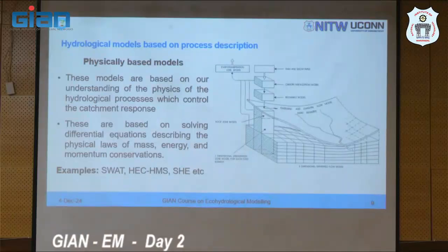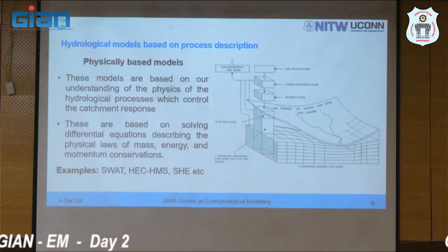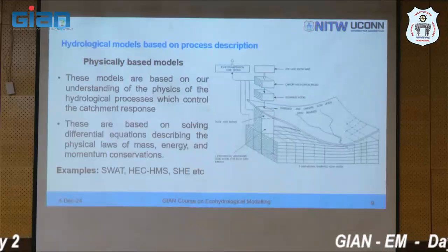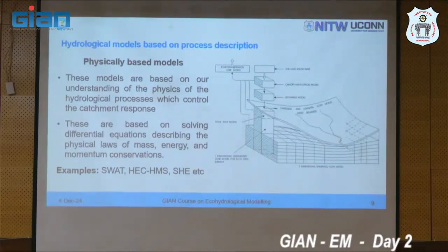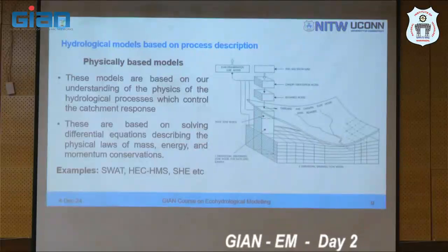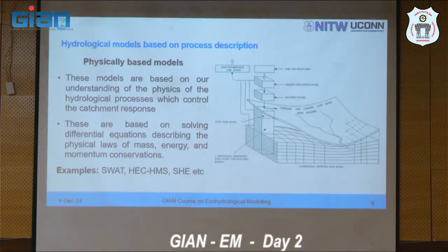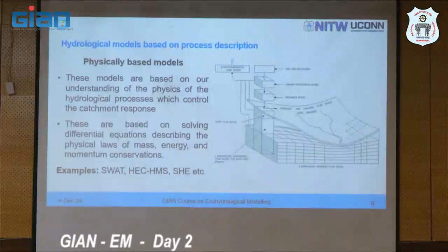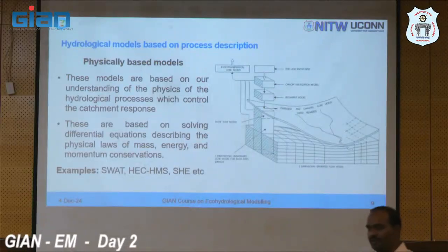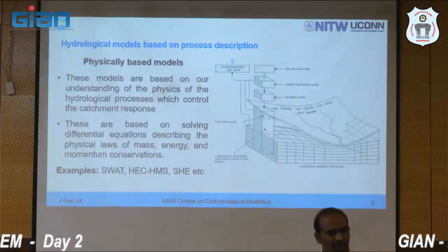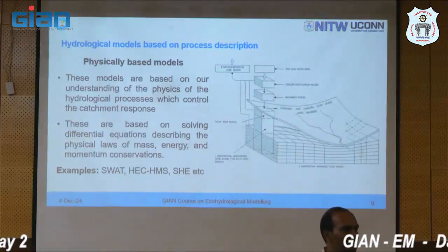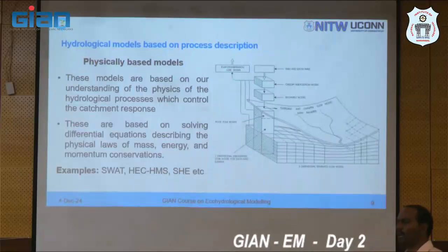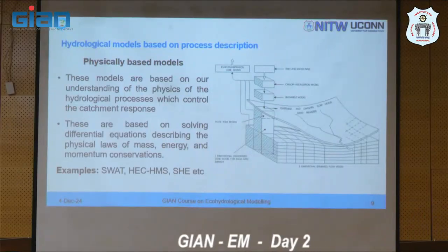So, these physics-based models started developing using water balance equations, basically using the conservation of mass. Change in storage is equal to input minus output, more of a systems-based approach. And that is where SWAT, HMS, and MIKE SHE are all there. SWAT, you can say is a physics-based model, but it also uses a lot of empirical equations. We call it physics-based because it works on the water balance equation, that change in storage is equal to input minus output, where input is your precipitation, and output is your runoff, evapotranspiration, groundwater flow, and groundwater recharge.